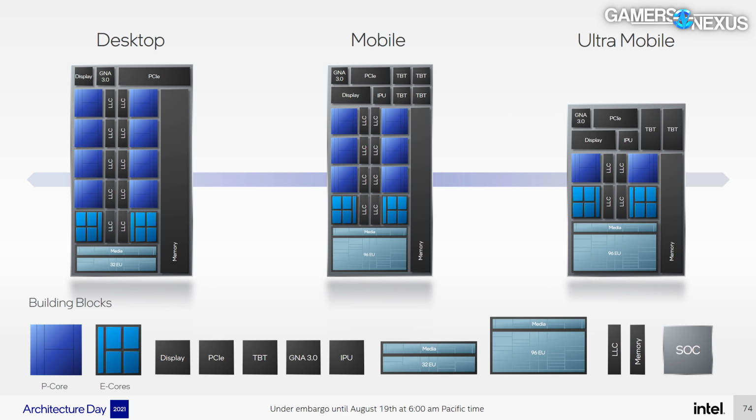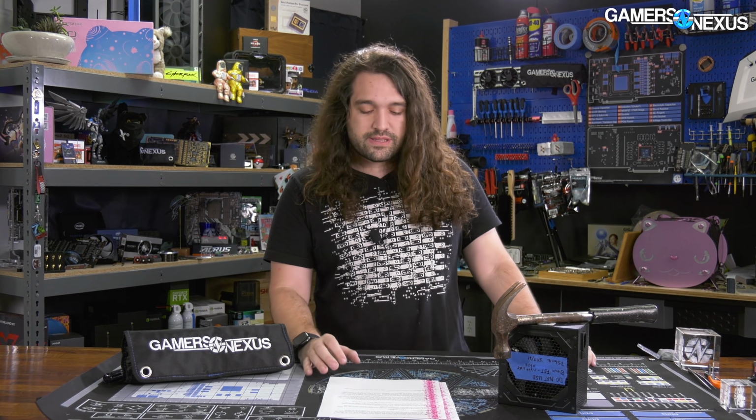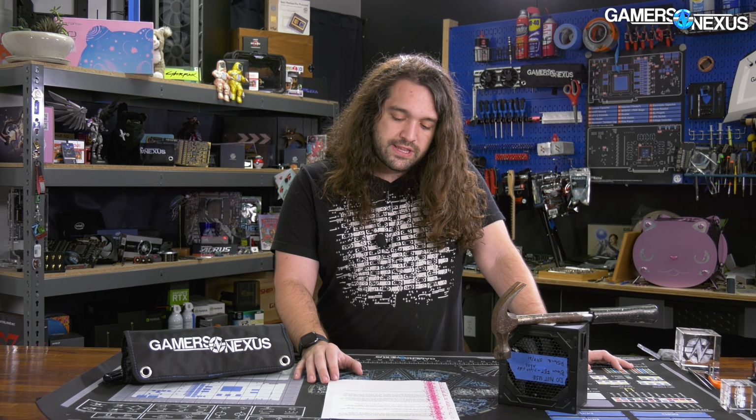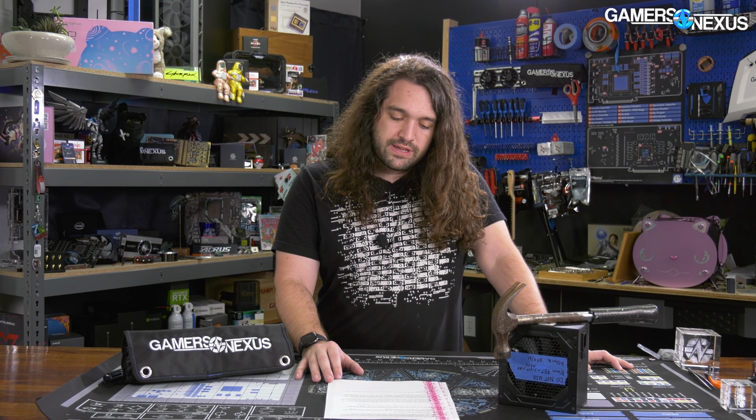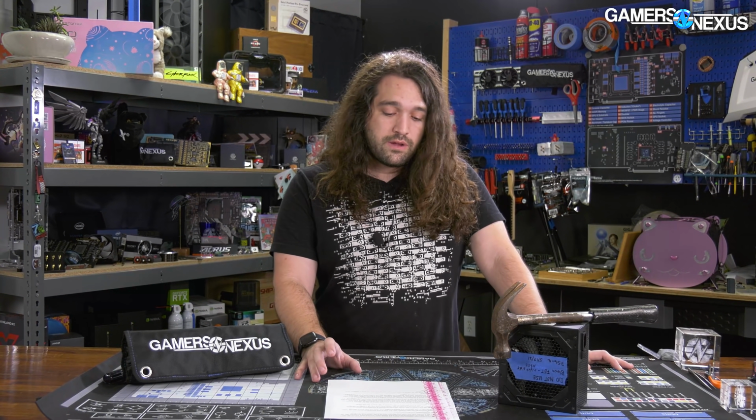The most striking difference related to the core differences we've been talking about is the proportional last level cache to core count on P cores. The desktop block diagram seems to only include the smaller 32 EU XE integrated graphics, and looking at the 2 mobile parts, they also consume about double the die space for graphics, and the mobile parts have dedicated space for Thunderbolt. So that's kind of the obvious differences between the 3 different product lines Intel's working on right now, and like other desktop parts before it, this desktop part is likely to rely on chipset support for Thunderbolt.